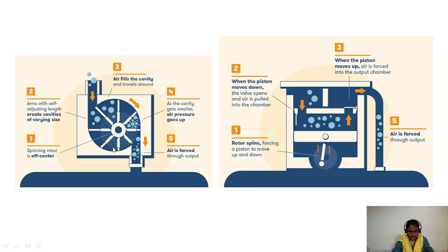Now first coming to the centrifugal compressor, which is shown on the left side of the slide. Number 1 shows the rotating rotor or rotating parts or blades. In the compressor, first the rotating parts will be rotated and the fluid will come through the inlet. The fluid is coming and it is filling up the gaps of the rotating part. As the rotating part moves, they impart energy, or they give their energy to the fluid, increasing its speed. But then it is allowed to move through the outlet, where it is allowed to move into a small volume.